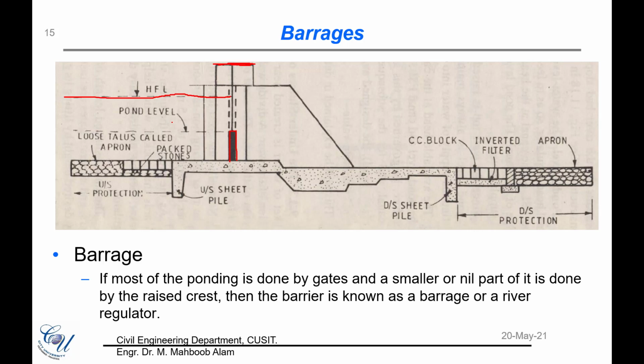There would be a delay in terms of the peak occurring at a particular time. So if there is a weir, the peak of the flood would occur maybe 1 or 2 hours later. So there would be this 1 or 2 hours where you can take certain precautionary measures. But the peak wouldn't be lower. It would be more or less the same peak as if there were no weir, so to say.